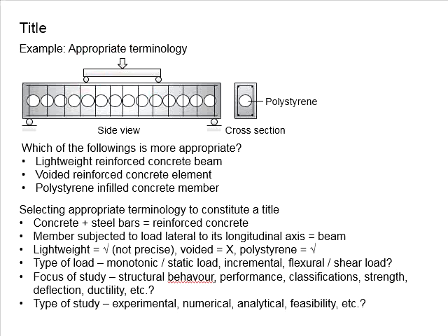Simply said, if the point load is close to your support within a certain range, the shear failure of the member is likely. Therefore, you are actually simulating the shear condition.